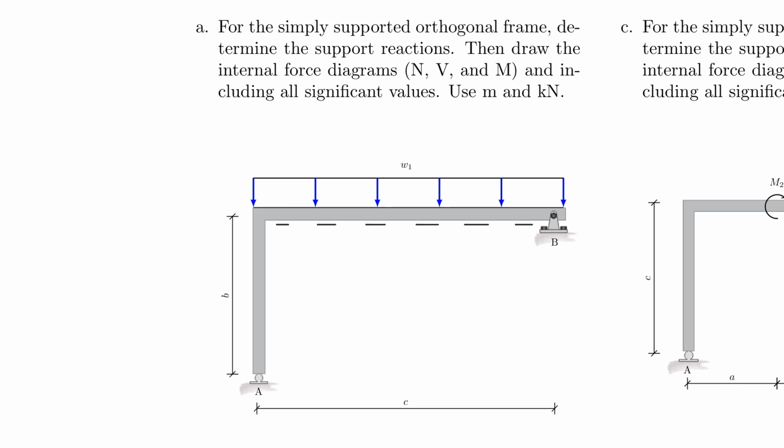Of course, you have used the reference fiber before, but you didn't really need it. In this case, especially for the vertical member, you want to identify if it's on the right side or on the left side. I choose to always put it on the inside, but there's no right and wrong about this, so you could also put it on the other side. In fact, you may want to practice and see what happens if you put the reference fiber on the left side.